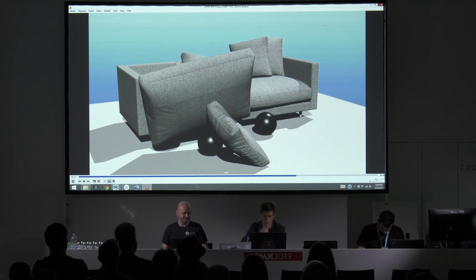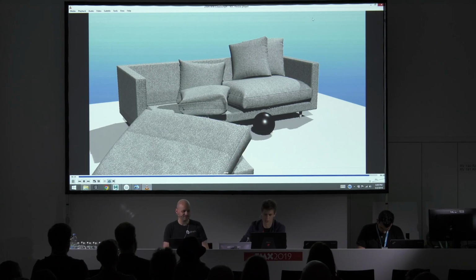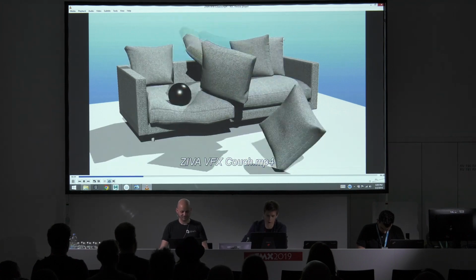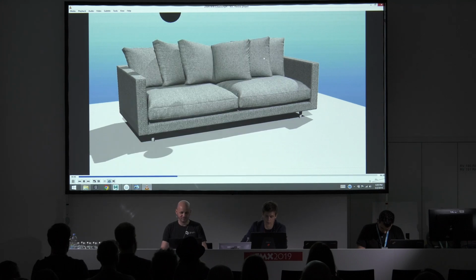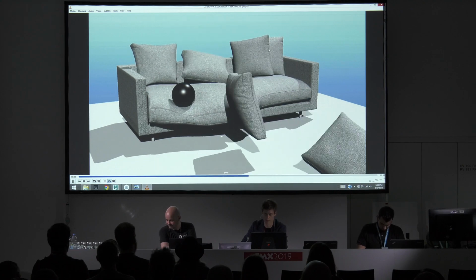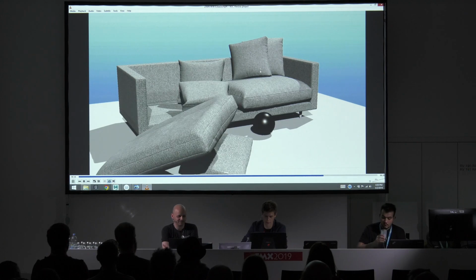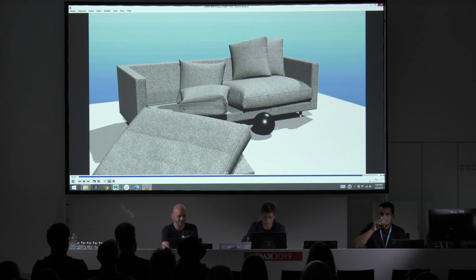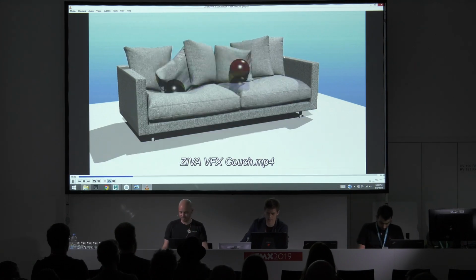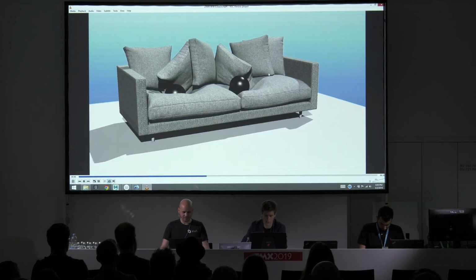The cool thing with our solver is that because it's using real-world physics, you can look up things like the Poisson's ratio on Wikipedia of different materials, like tissue or bone or wood or foam, and you can plug them into our solver, and it should give you the right result because it's using real-world engineering stuff. So it's a nice thing to bear in mind. These bowling balls are also tissues. They're very stiff, obviously, and I've just cranked the density up on them. So you can represent quite a wide range of different materialities.